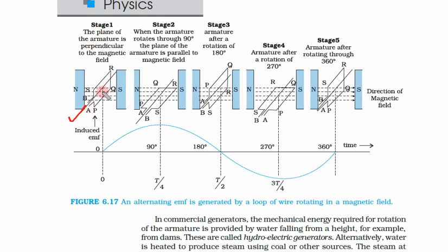So here this is the first step, stage 1. Here we can see this area vector and magnetic field both are in the same direction. Now this is rotated by 90 degree. Further rotated, now it is 180 degree rotation. Here it is 270 degree rotation. So this 90, 180, 270 and then comes back to the same position. So initially EMF was 0.